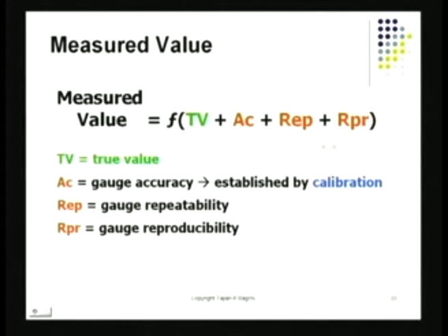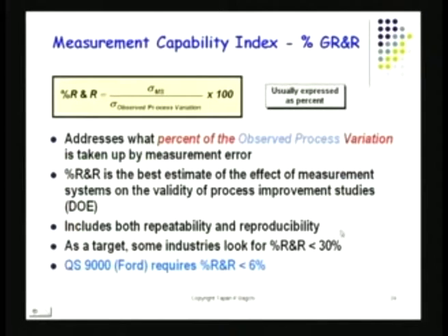These are the different factors that impact the measured value. This is the observed measured value and the true value is here. Unless I have a decent idea of what these are, I will never know what the true value is, because all that I am observing is this. If these values are unknown or large, then I might think I have an idea of the true value, but in actual fact I do not, because of these hidden things which are also inside the measured value.